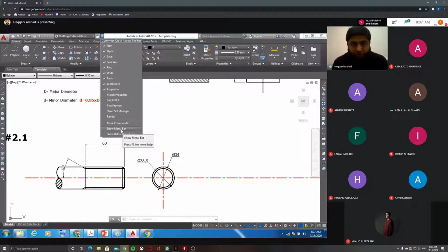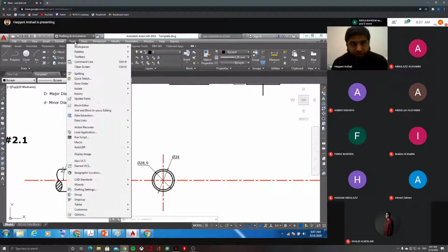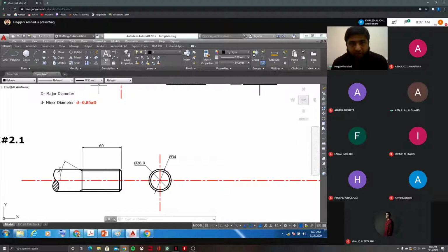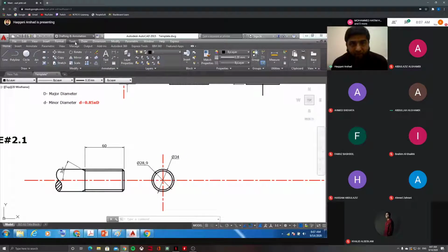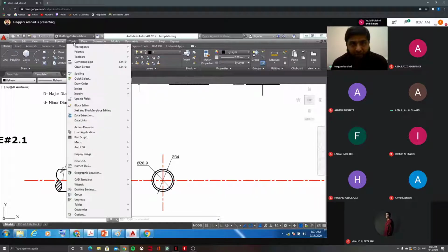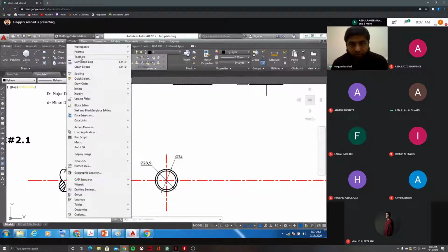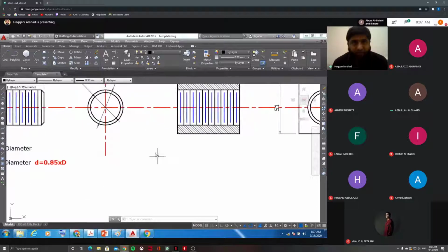If you want to see the tools as well, just click show menu bar, and after that you see the tools option at the top. From this tools option, go to toolbars and then AutoCAD, and now you can add whatever toolbars you want. For example, I remove Modify like this. Now I want to add some toolbar on the left, right. So tools, toolbars, AutoCAD, draw. It will come on the left. Then tools, toolbars, AutoCAD, modify, like this. You can add the toolbars. Okay. Thank you. Okay.